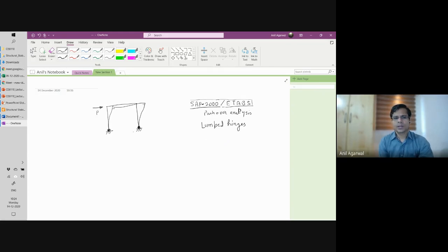What does that mean? What it means is that for typical structures which are like these, usually what happens is that the bending moment diagram is not uniform. The bending moment diagram varies like this. Okay, let's say I'm drawing it on the column. So it typically varies like this. So there is a nonlinear, non-uniform bending moment in the cross section. It is highest at some location, lowest at some location, and again negative highest at some other location.